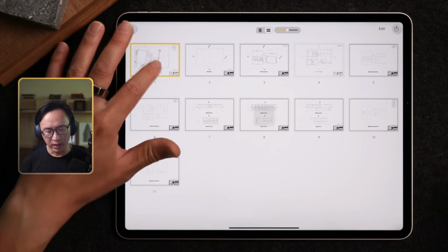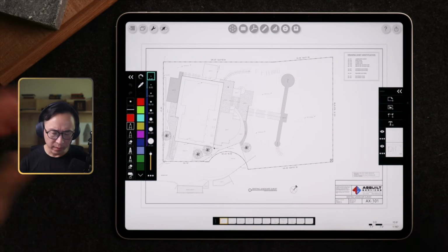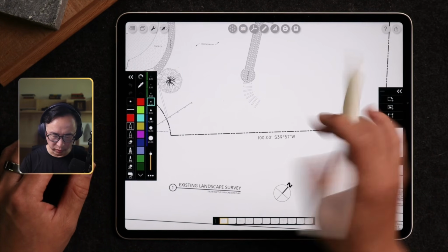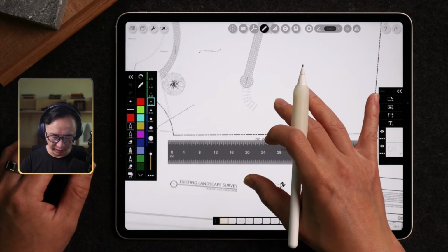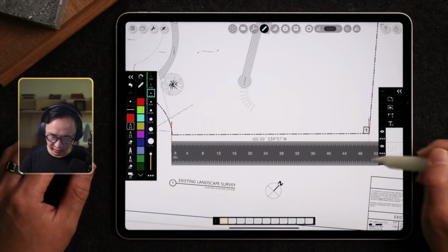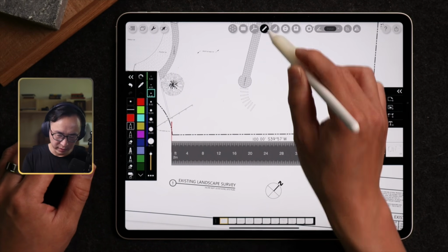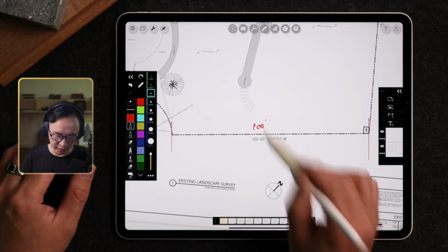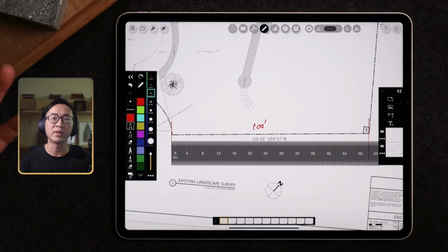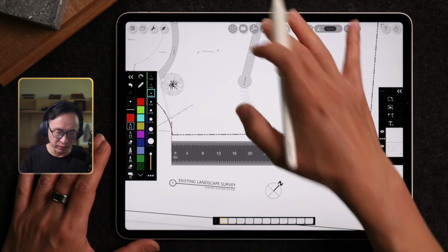For example, if your site plan is at 1/8 of an inch, which is a smaller scale, you're not going to be able to pull up your ruler and verify that from this end to this end corresponds to the scale. You can see that on paper this is 100 feet, but in scale this is 50, because we didn't assign the right scale to this site plan.